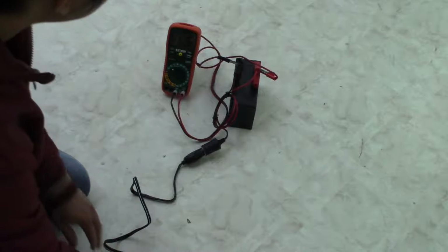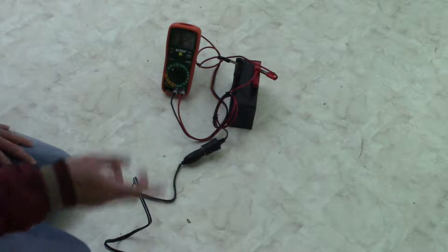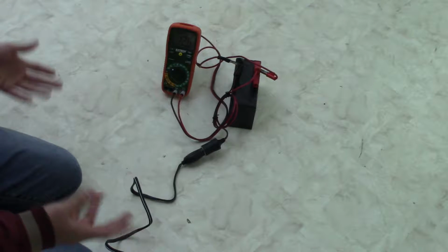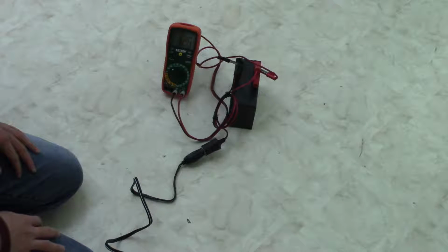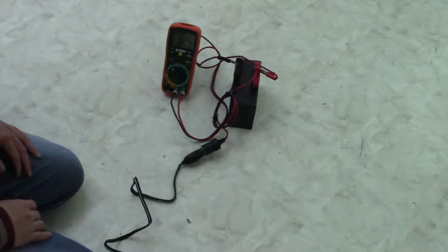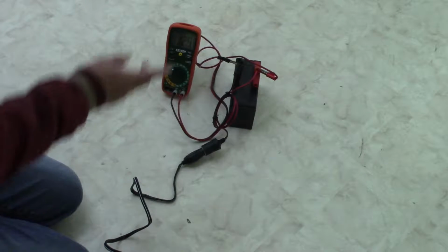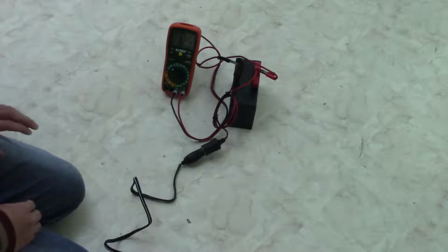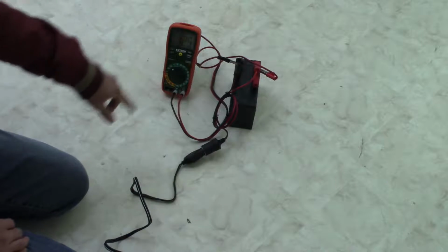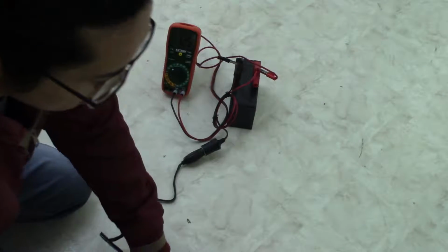Okay, let's go ahead and run this first. So the voltage dropped to 12.5. Let's go ahead and turn this off again. 12.6, wait for a few seconds, still 12.6, let's turn it on, 12.5 already. As you can see, the current has dropped the voltage just a little bit. Because of the internal resistance of the battery, there's a voltage drop, that's what I meant to say.